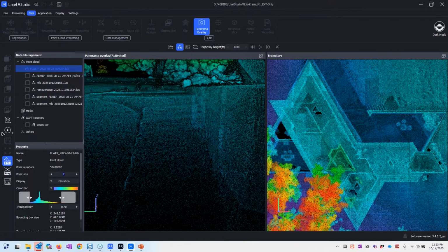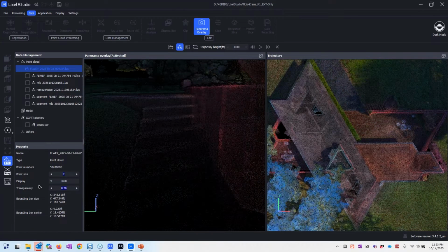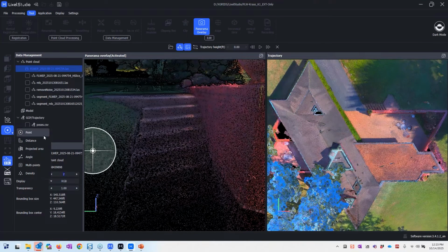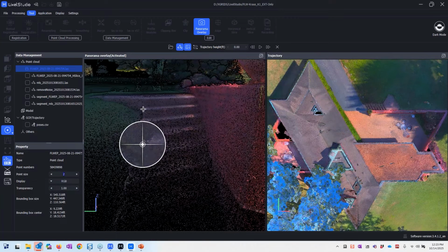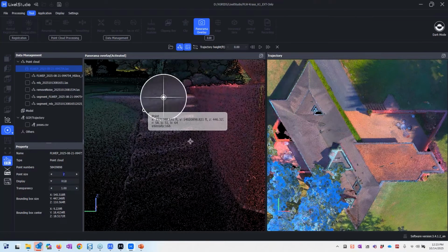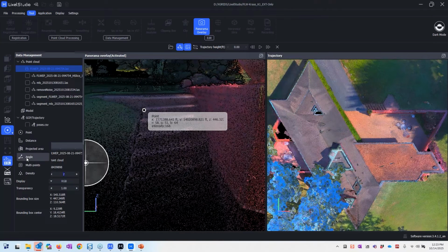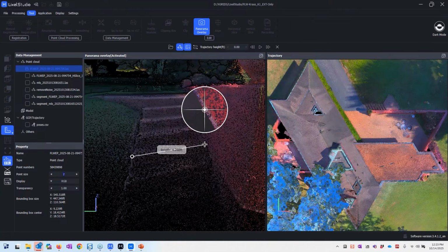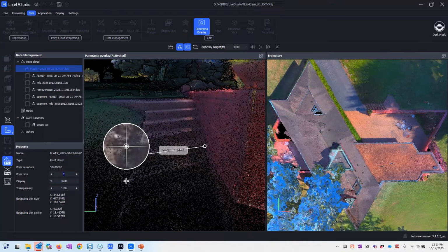Okay, and I can take measurements in this view. So going back to, let's go back to just RGB. Let's increase that back up to 1. Let's turn on the image background. So there are basic measurement tools in here, like point. If I wanted a point elevation, I can just say point, pick a point, and then it gives the information about that point. Take measurements in here, angles, distances. You know, I want to know the width of these steps. I can use the little target to help me make sure that I'm collecting that along, and get lengths and take measurements in here.